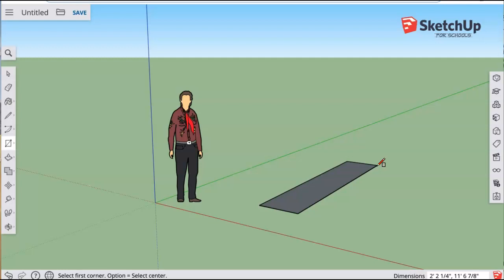So I'm going to type in my bottom dimensions, which are going to be the 3.5 wide and the 42 inches deep. So I'm going to type in 3 space ½ inch, comma, space 42 inches. Now if you'll look at the way I've typed that, you'll see that the inch marks are quote marks. This is very important.